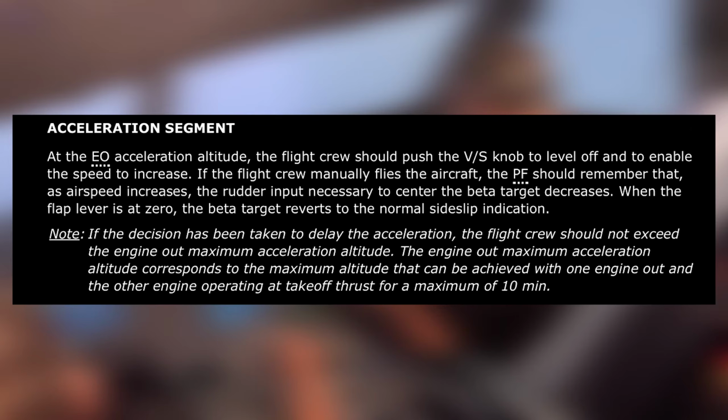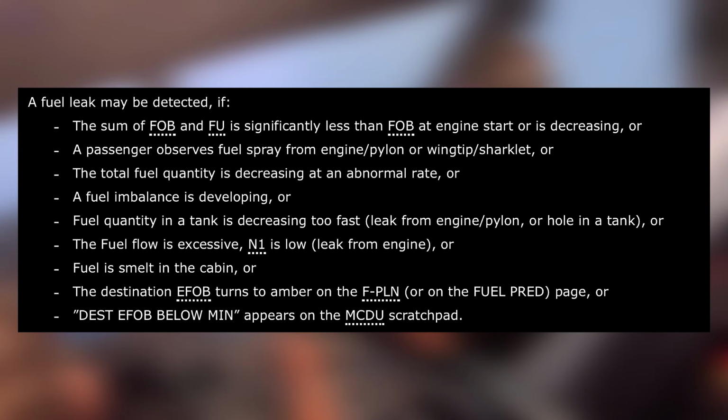Maintain the thrust levers at the current position. A common error is to command TOGA at this point, which will result in an undue activation of the go-around phase. As for John, he reaches the fuel leak conditional statement. He will diagnose if there's a fuel leak to determine whether or not the subsequent ECAM actions apply.